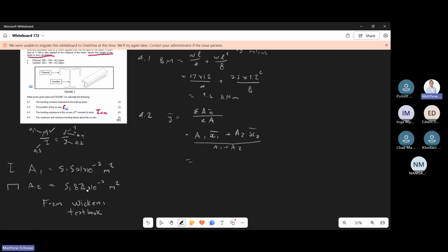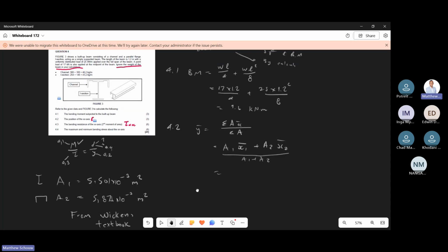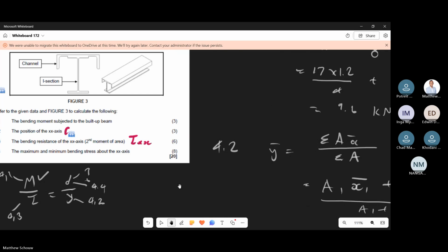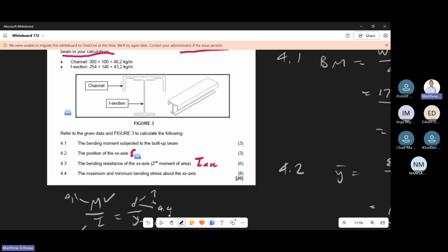So what we've basically got now is that area, that area, that area, that area. So now we need to get these X bars. What the X bars are is essentially from a reference point to that element's particular section. Let me zoom in here quickly. You need to find the center of this particular thing. We can use the top or the bottom. If you watch that video, I nicely articulate that, I believe. So we're going to be using the bottom as a reference.